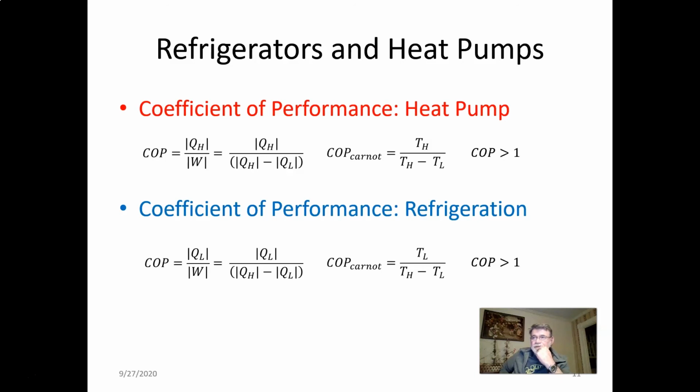And the COP generally exceeds 1, especially in heat pumps, because instead of just converting work to heat, it pumps actual additional heat from a heat source to where the heat is required. So we can roughly compare the COP to the heating capacity of a heat pump to the amount of electricity required to operate the heat pump in the heating mode.